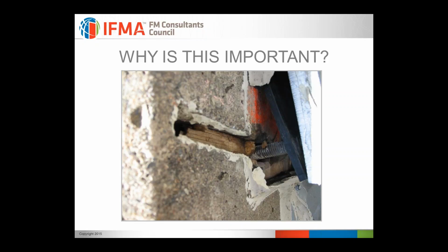Here's what happened. In that wall, there were remnants of the formwork that were left in place. This wood block, this is the bolt that was supposedly installed in the concrete wall. Nobody really knows what happened that day that the contractor drilled the hole in the concrete. He was drilling hundreds of holes to install all these anchors. Came across this one, and actually there were others that subsequently we've discovered where it wasn't installed into concrete. It was installed into a wood block. Nobody knows why.